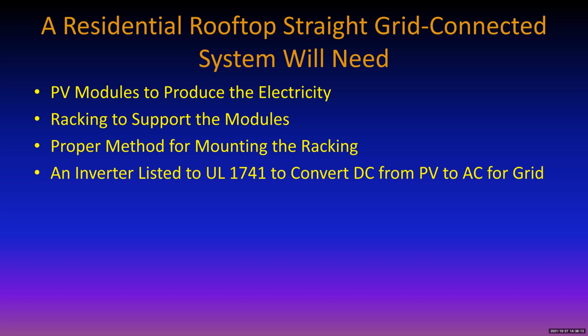And the main thing is that UL 1741, which is the testing provision for IEEE standard 1547, is that the output of these inverters has to be at least as good a sine wave as the utility. Well, the utility is allowed 5% total harmonic distortion, which is the measure of the quality, and 0% means perfect sine wave. Most of the inverters on the market right now have less than 3% total harmonic distortion. So in fact, the output from an inverter is generally better than the utility output. So that's something you can do electronically very readily.